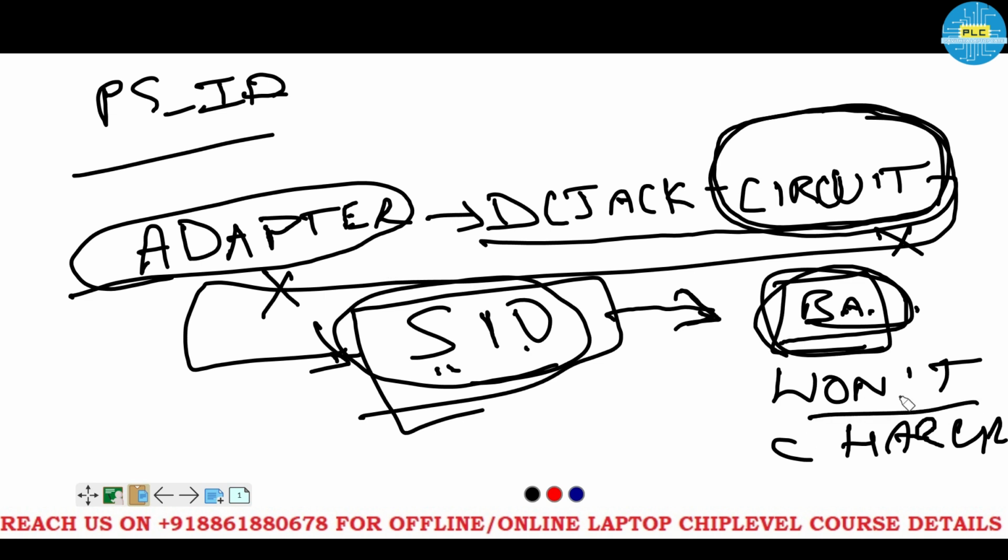That is the concept. Okay, intentionally or by components or by track mismatch or DC mismatch, whatever it may be, if some components in between are interrupting the adapter information from reaching the Super IO, then you will get what? An adapter unknown message or not installed or some other issues.